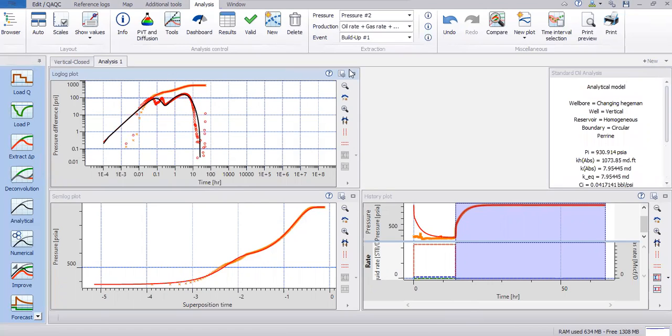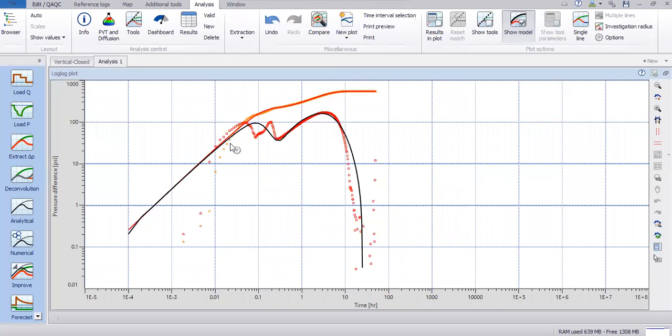All right, so yeah, you can, yeah, this one, something like this. So this is my advice. If you find this weird looking derivative, you can say most of the time that's not reservoir characteristic, that's wellbore or near-wellbore phenomena, right? So I'm not going to honor that. I'm not going to be focused on that too much.